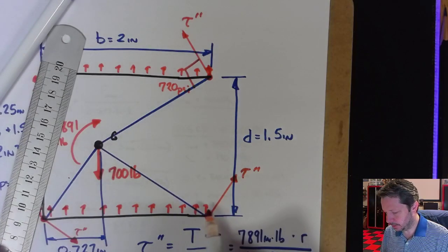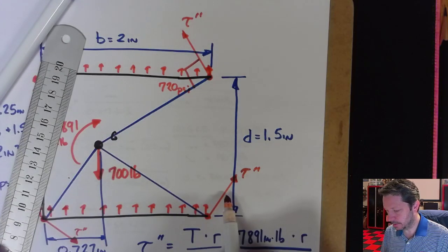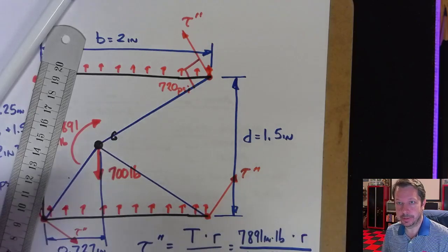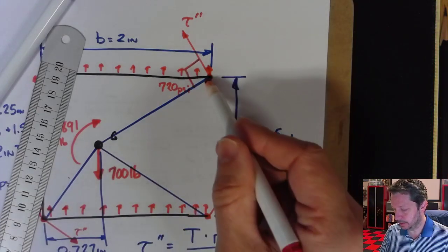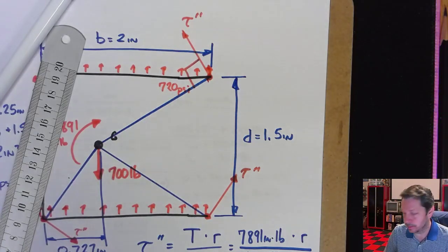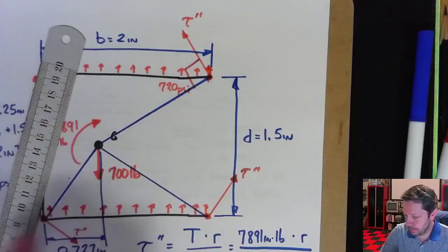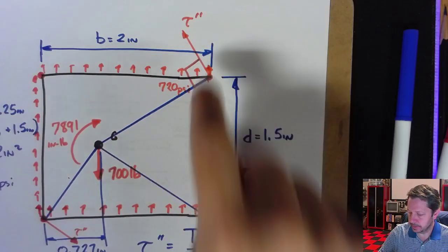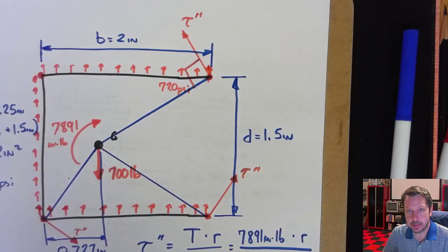And positive Y components on the primary and secondary, so they add just like this one. The only difference here is I have a positive X and a 0 X on the primary shear, so they would create the same effect. So either this or this are going to have the same total shear stress on them, and so they're going to be equally bad points to deal with. All right, so let's just look at this one.